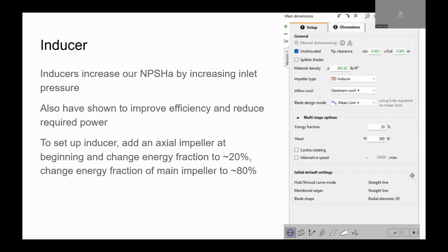It's probably getting out of the zone where an inducer would be the optimal machine, right? If too much of your pressure comes from the inducer, then you might as well make it an impeller. Yeah, that's probably what's going on. But if we're 3D printing, we could maybe stick an inducer on there. I think it's something to look into.